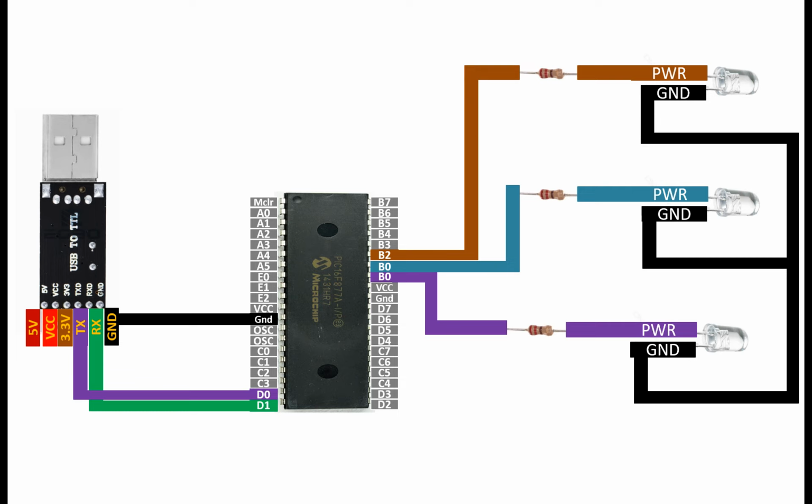Now the ground pins, just common them and send it to the common ground of the PIC. In this way, our connections are completed. Now before we move on to the programming, let me introduce you to the hardware.